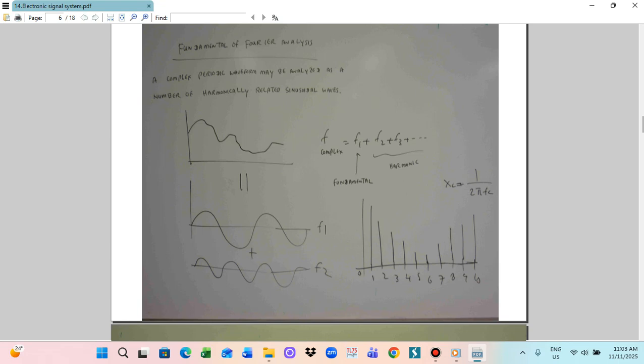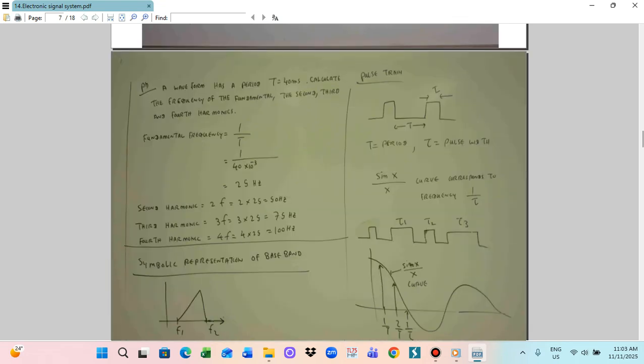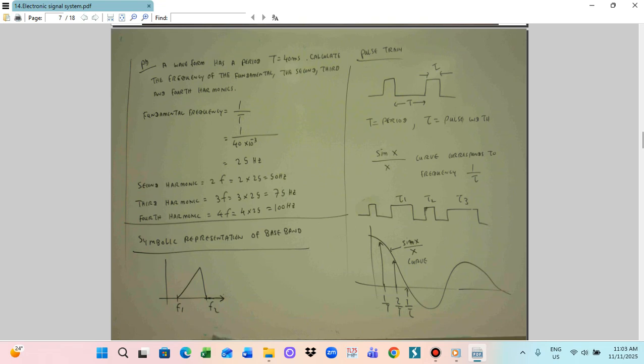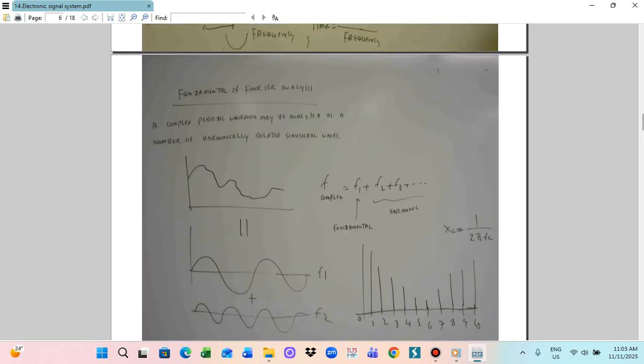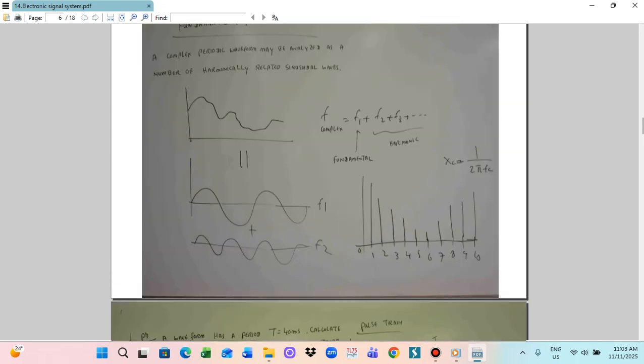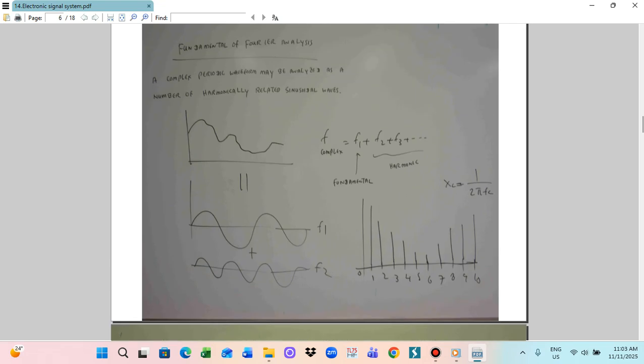After you know, you need to subtract the second or third harmonic. You have to design the appropriate filter. A filter uses a capacitor: Xc equals 1 by 2πfC. Depending on the fundamental frequency value, you can select the appropriate capacitor value. By selecting the appropriate capacitor, you can eliminate the harmonic frequency. In this case, you have to utilize a high pass filter, a low pass filter, or a band pass filter. I gave you those in analog electronics. Those kinds of filters are utilized to suppress the unwanted harmonic frequencies.